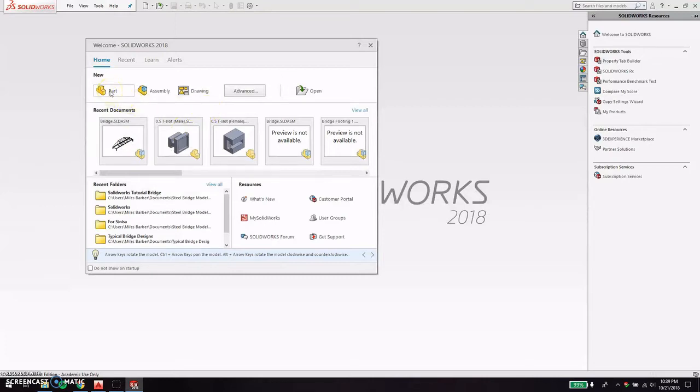When you do open up a piece, when you save it, just make sure that all of the pieces are saved in the same folder, because assemblies refer to other parts. They refer to parts to actually put everything together, and so if it can't find the part, it just won't load it. So sometimes, if you screw up and you put your pieces in other folders, the assembly will give you an error, and the assembly will have like holes in it basically for parts that are missing.